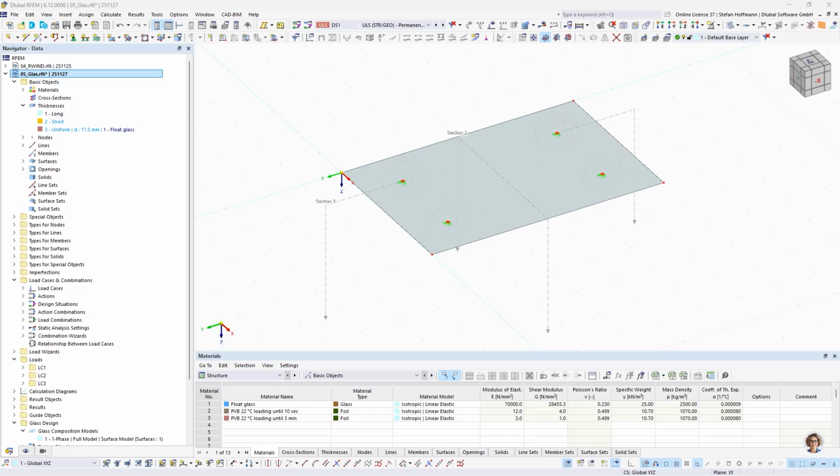But in the next chapter, 7.2.2, in the case of an unfavorable shear coupling, e.g. in the case of restrained stresses, full shear coupling must be assumed. So you usually have to consider both states in your calculations. Sometimes, of course, you cannot see the effect of the shear coupling just from an engineer's point of view, but it's quite easy, and we will show it in this model.